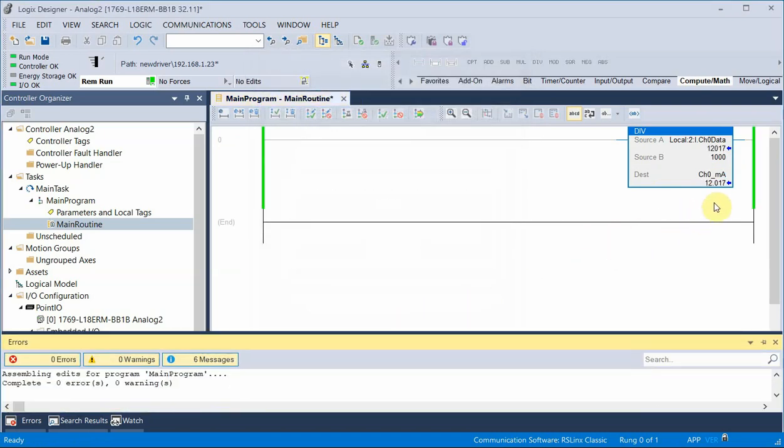And you'll see that 12.017 milliamps. If I go down to 4.3, that's off by quite a bit. I don't think it was responding there. Let's try that again. Okay, 4.0 on my transducer, 3.96. So it's off by 0.04. So again, I could get data points and come up with an equation to straighten that out, but let's let it go with that. So what can I do with that?